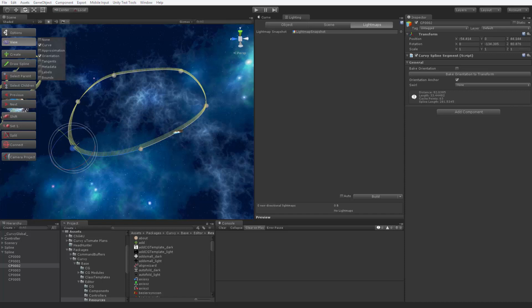The dynamic mode gives you the greatest degree of control over spline orientation. For example, you can add new control points anywhere without disrupting the orientation, which is completely decoupled from them until you explicitly mark a control point as an anchor. That's what I'm doing right now. Note how rotations of those points have no effect on orientation, which continues smoothly from one anchor to the next.